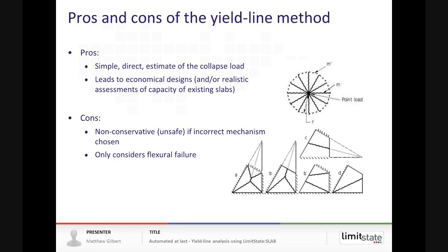Cons are it is unsafe if you choose the wrong mechanism, and another con, I guess, is that it does only consider flexural failure, so it doesn't tell you anything about, for example, serviceability, deflections or cracking, and it doesn't, for example, consider other failure modes such as shear failure.